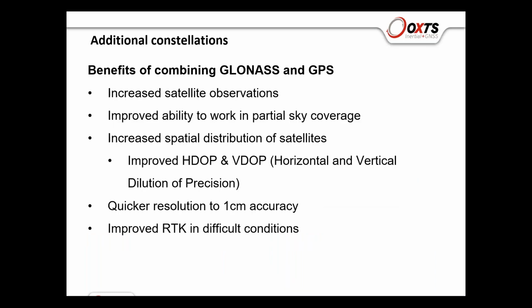The benefits of combining constellations. You get increased satellite observations and improved ability to work in partial sky coverage. You get increased spatial distribution of satellites and quicker resolution to 1 centimetre accuracy, and improved RTK in difficult conditions.